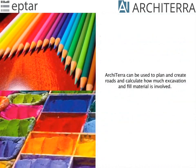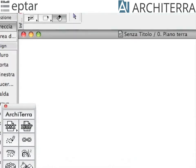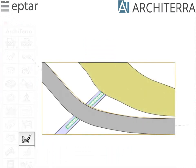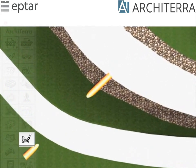With ArchiTerra, you can let the imagination run free, coloring the terrain with any color and material. For example, to create the course of a river with a different material from the meadow, you can define the area with a fill, then set the graphic characteristics using the Colored Area tool.